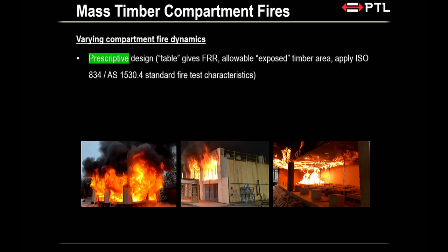What does that mean? It means that I'm reading a table. The table will tell me what the fire resistance rating is, and also how much exposed timber surface I'm allowed. And I'll basically tell that to my design team. I'll tell the structural engineer that I need 60-minute FRR. That's it.